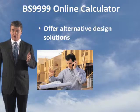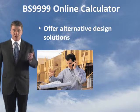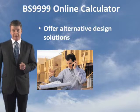It will also offer you the facility to offer your client alternative design solutions based on the fire safety facilities in that building. This online calculator has been designed to make the application of BS9999 easier and give you the facility to carry out a sensitivity analysis to vary parameters and identify immediately what's the impact on the staircase sizes of putting a mist system in, of putting a sprinkler system in, what's the impact on the travel distances by having early warning. It allows you to vary parameters and instantly see the impact.